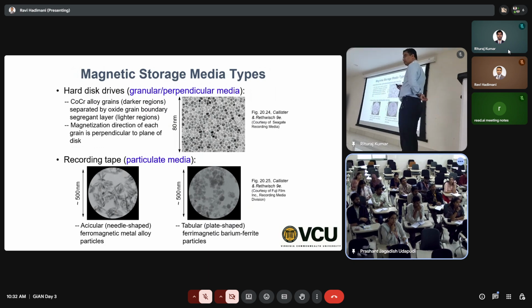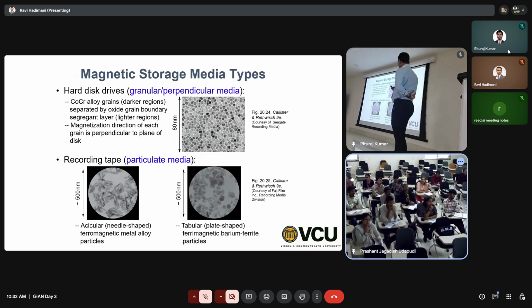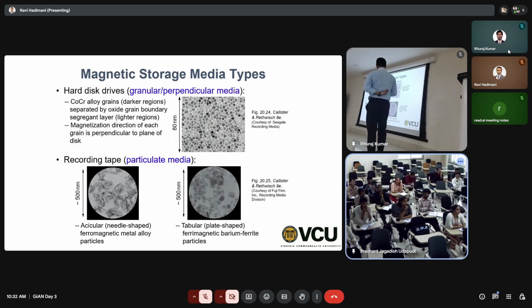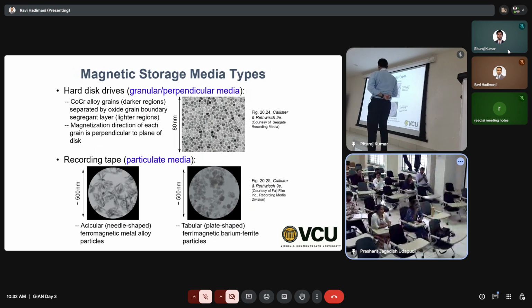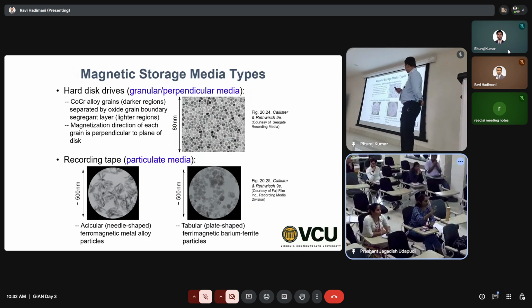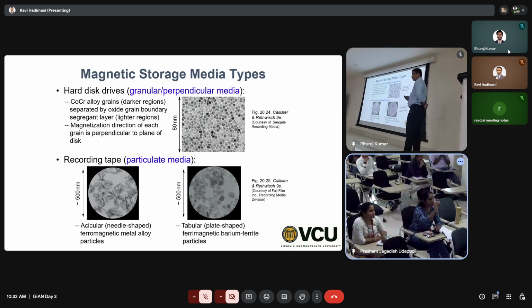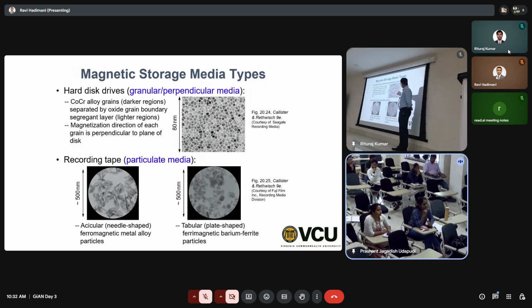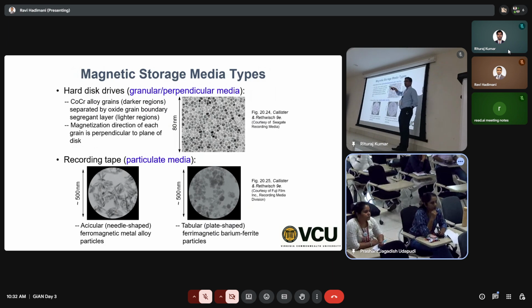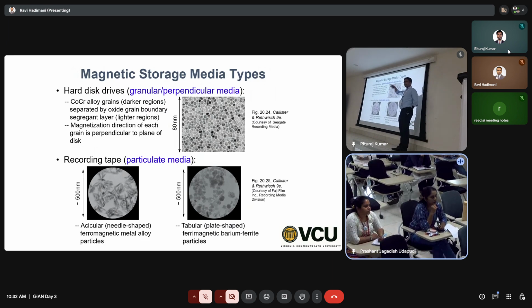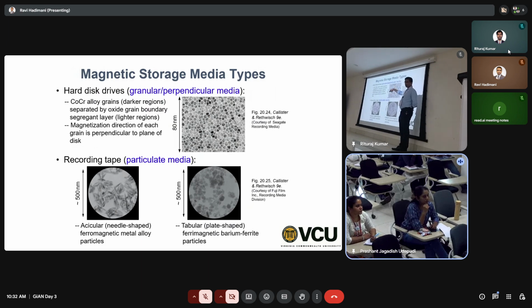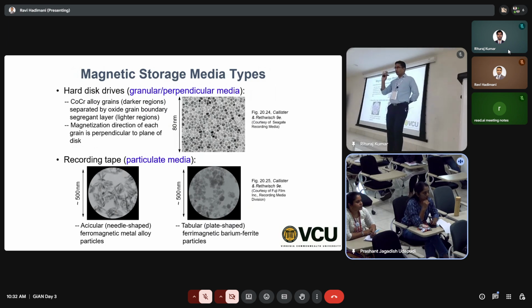The center shape of the white thing is an oxidized one. So when they are not reading, only the grain size reads. So is it that only the darker surface is where the data is stored? It doesn't matter. You can choose whether you want to have the darker side as +1 or -1. You magnetize or non-magnetize. You magnetize in one direction or the other direction. But the concept here is each grain you can magnetize in one or the other direction.